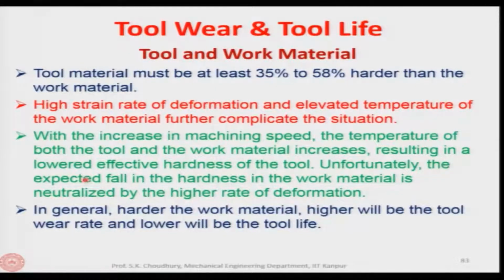Unfortunately, the expected fall in the hardness in the work material is neutralized or compensated by the higher rate of deformation. You understand that higher rate of deformation means what? High resistance to the deformation, that is high strength. So, what is happening is that the more plastic deformation is imparted to the workpiece, the more will be the resistance. So, the apparent strength of the workpiece is increasing, as if.